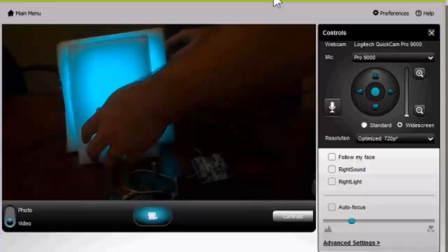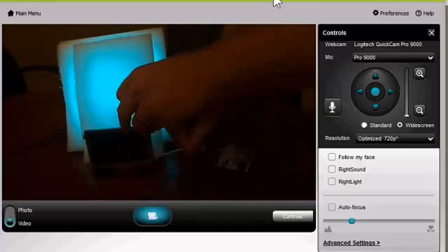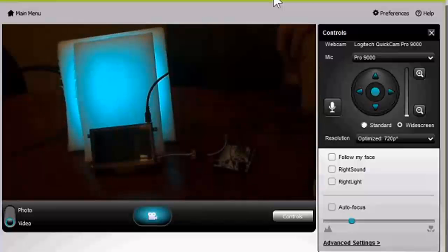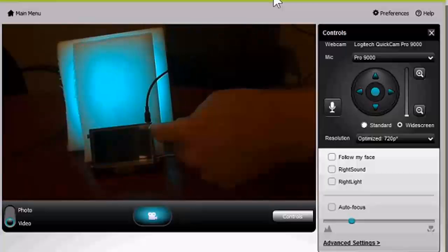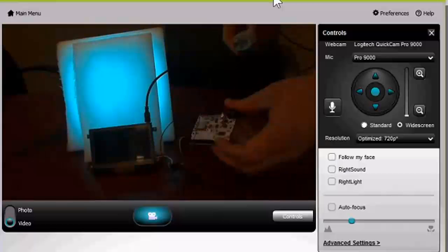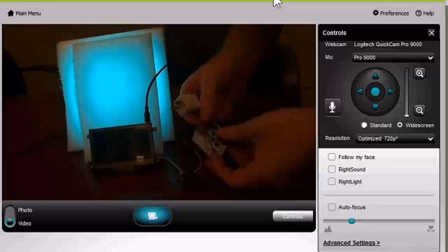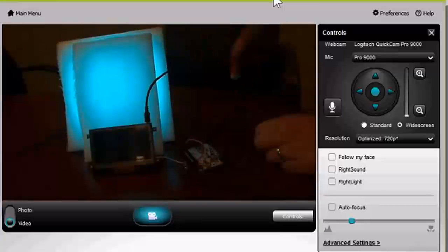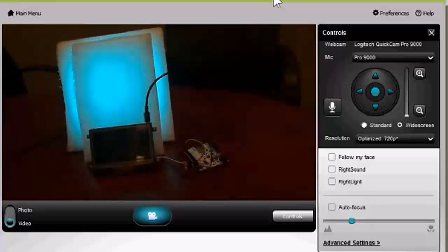So I'll turn the light on, give it a few seconds to connect to the Wi-Fi, and then plug in my module. This is only for power. So the Amulet display is connected to the Espressif module through the serial port, and then these two are just power and ground. And plug it in. And it's going to take a few seconds to boot.